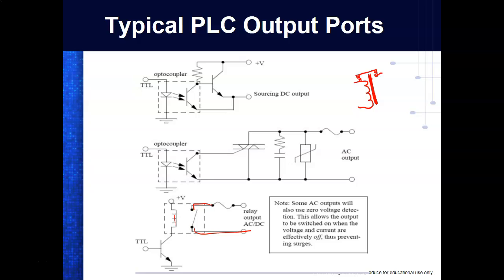It had a regular wall switch on there, and that's what he put. Because a wall switch doesn't care if you put DC. It doesn't care if you put AC. It's just a switch. So yeah, you could use that as long as you don't exceed the voltage rating and the current rating on it. You could switch DC with that. You could switch AC with that. Of course, with a wall switch.